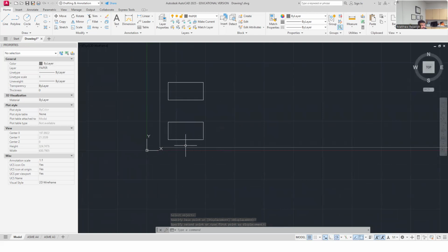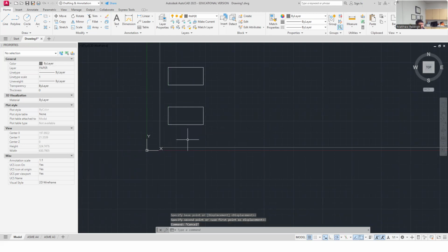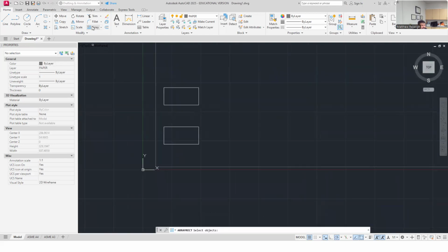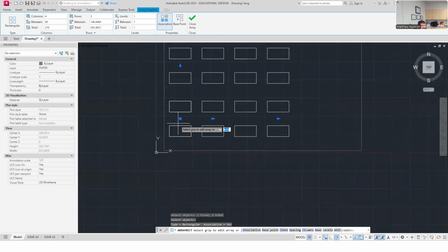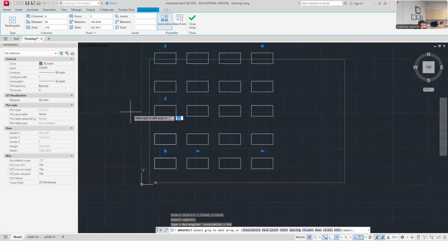That'll be great. On the paper, I'll probably add more space here than I really have. I can move those if I select them both now. If I can select that, there we go. Maybe on my paper it'll actually be something up here like this. And then I'm just going to array this as a rectangular array. I'm going to select both of these objects that I want to array, and they're already showing up because now I got the ribbon menu as an array control.